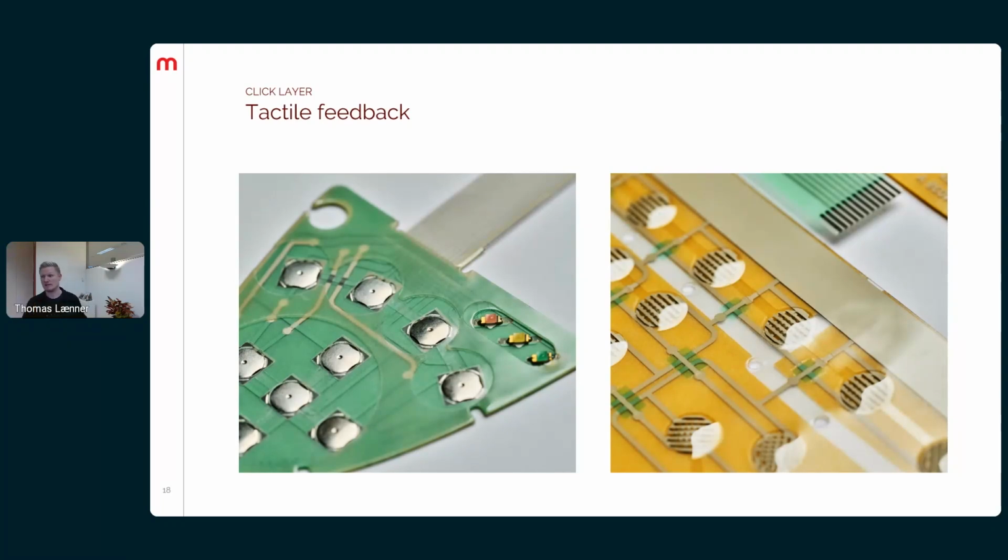And talking about the click layer. In membrane keypads, we generally have 2 ways to achieve the click. Either by metal domes, as you see here, which has a very tactile and clear click, or we can also use polydomes, which is a solution where you actually emboss the materials to make it like just shown previously, having the tactile feel in the actual embossing. Metal domes are used in many cases. It's almost standard, but in some cases it could be worth considering polydomes when you have requirements such as low click volume or something like that.